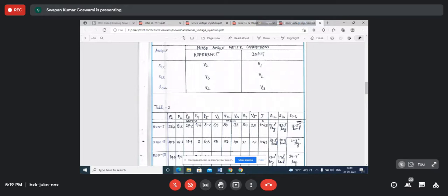And what are the powers? P1 is 25.3 and P2 is 19.2. So from N2, 19.2 watt is the power coming out, but the power ultimately reaching N1 is much larger. It is 25.2. How? Because of that series injection transformer. That means with the series injection transformer path, another power is being added. How much is that power? That is P5, 8.2, but P4 was 9.6.